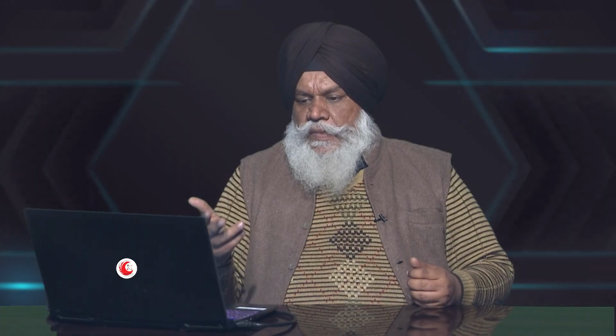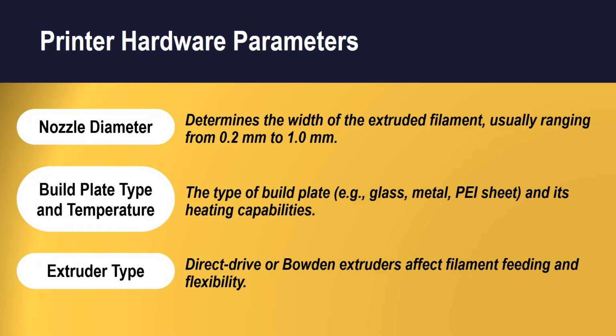Then specifically the extruder type. As you have seen, I have an arrangement in the liquefier zone, and some mechanical drives are there, and I am basically pushing the filament to pass through the nozzle. So the extruder type has been categorized as direct drive or Bowden extruder, which affects the filament feeding flexibility. What I have seen in my work, the direct drive is a little more comfortable if you want to work on changing the filament again and again. But of course, in multiple heads, we need to work with the direct drive only.